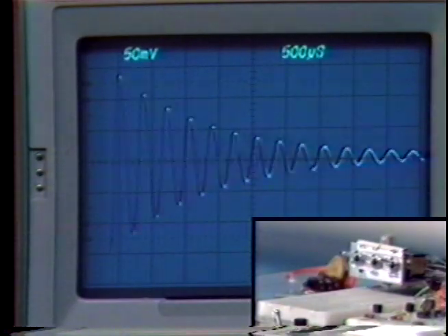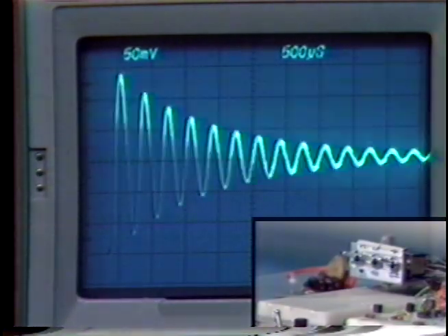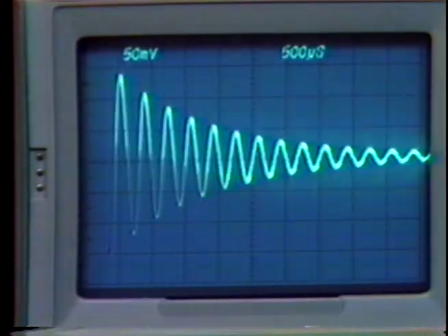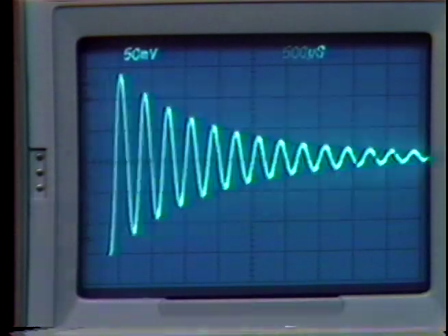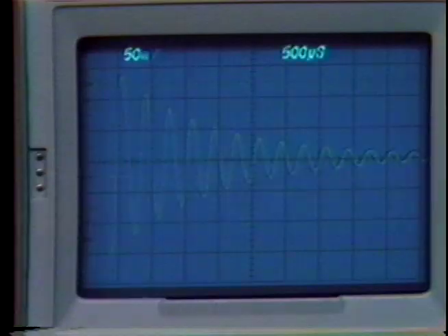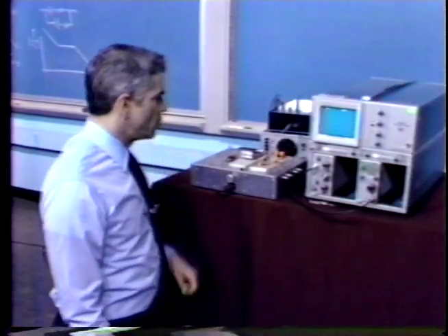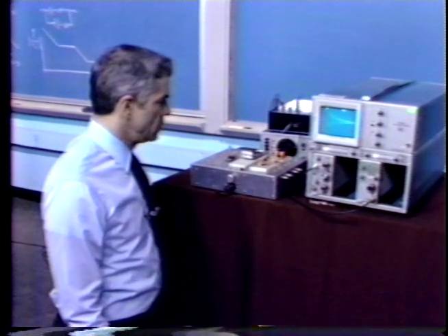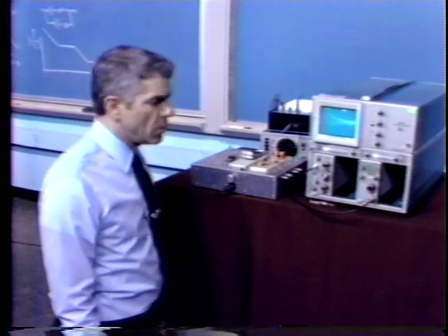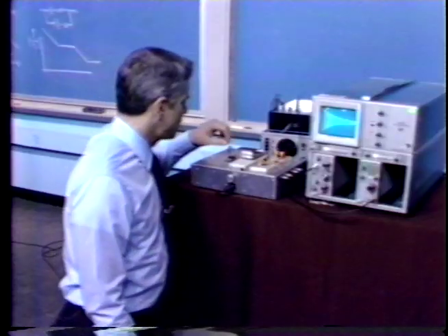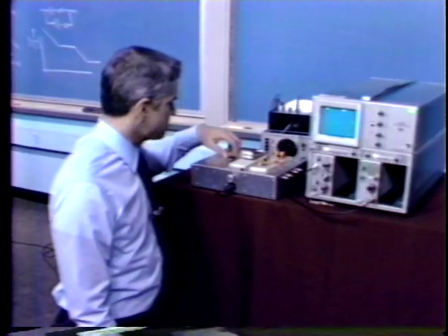Here we are again with a transient response that corresponds to a 1 kilohertz pole location associated with R1, C1. So we see that when we use that sort of compensation, the 1 over S compensation in a loop, where we can add an additional pole, we're able to get into very, very severe stability problems.